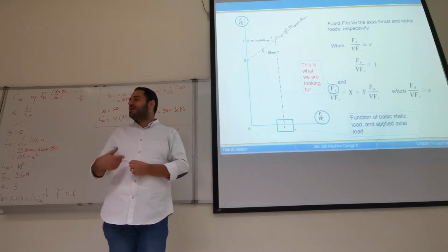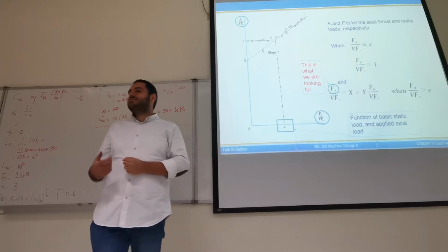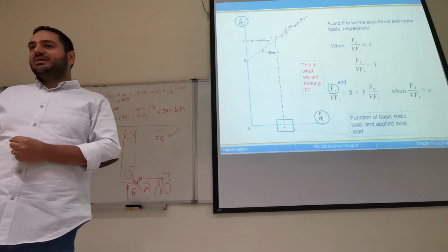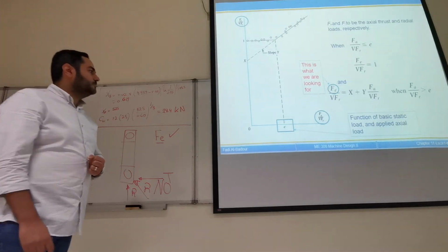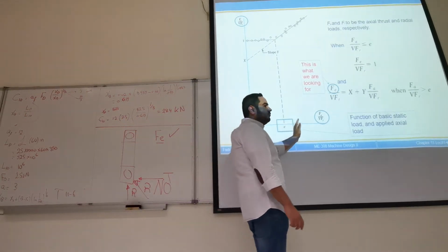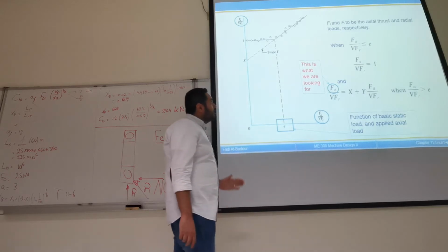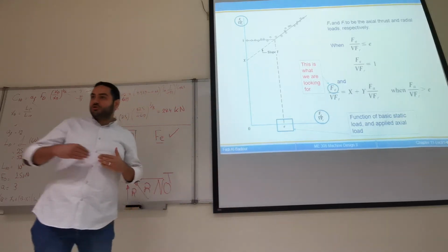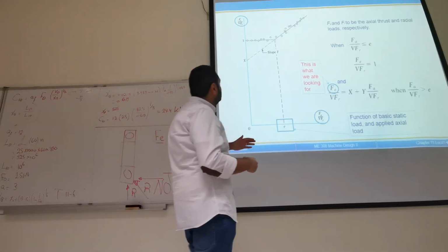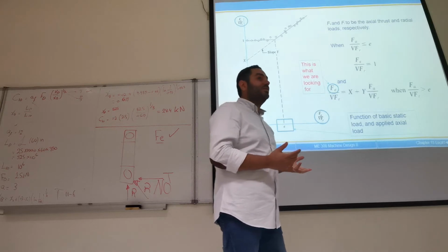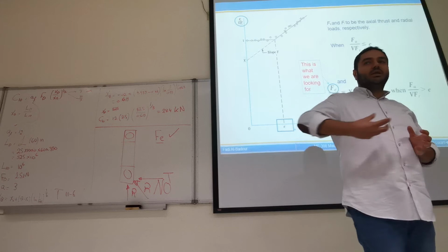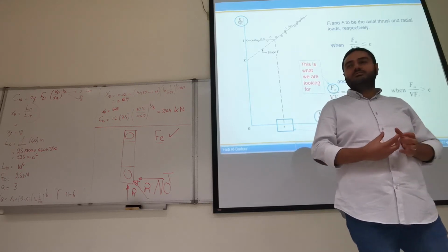It's just like the bearing is not seeing that thrust load; it's not affecting the bearing in its life or in its fatigue life. So you don't consider it. But after a certain ratio of thrust load to radial load, you can see there is a trend that can be considered linear. This trend shows that the equivalent load is becoming greater than the radial load. Why is it becoming greater? Because thrust load is now contributing to the damage of the bearing.